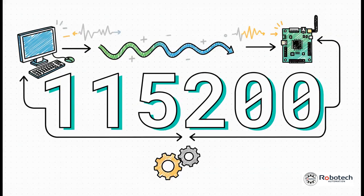So what about that number, 115200? Well, that's called the baud rate. It's just a fancy way of saying the speed of the conversation. It's super important that both your computer and your ESP32 agree to talk at the exact same speed. Otherwise, it's all just going to be garbage.